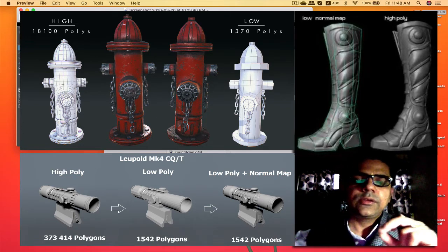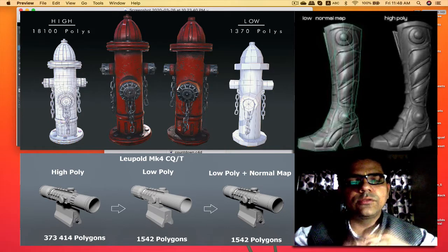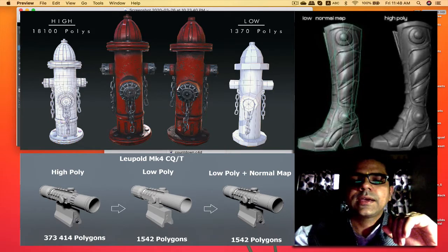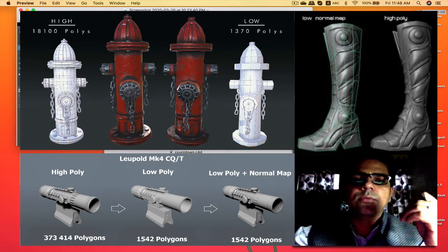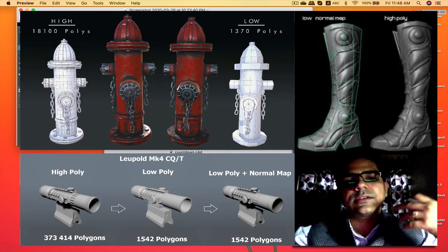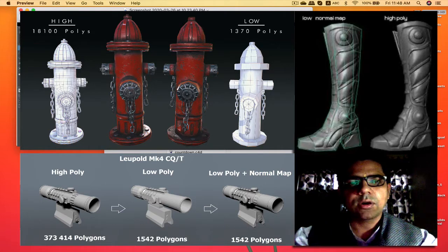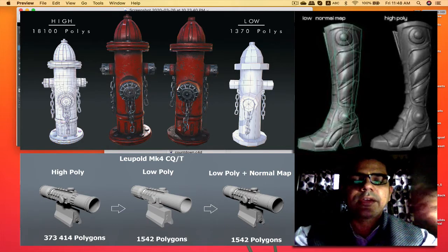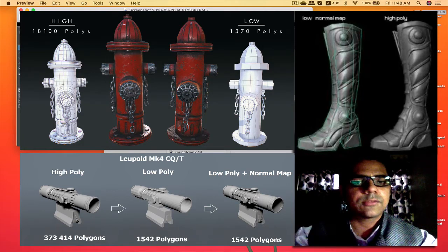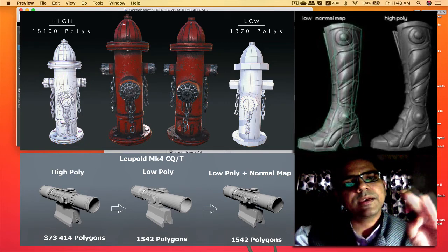So basically, you first create a low poly model. In the second step, you UV map that low poly model, and in the next step, you take a copy of that low poly model and add some more resolution to it, and probably take it into applications like ZBrush or Mudbox or Substance. Create your details and then bring that geometry back into Maya.